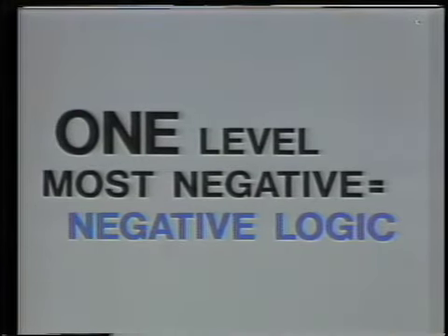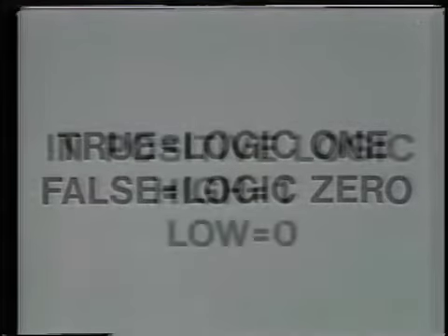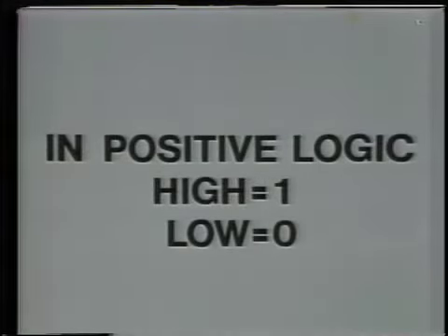The circuits shown in the remainder of the course all use positive logic, but there are many older schematics that were drawn using negative logic, so you should be aware of the existence of the two forms. In circuits where the logic levels are referred to as true or false, a true and a logic 1 represents the same thing, and of course a false is the same as a 0. The logic states called high and low refer to voltage levels, and it's necessary to know whether you're dealing with positive or negative logic in order to relate highs and lows to trues and falses, or to ones and zeros. We're using positive logic in all the following material unless otherwise noted, so any reference to a logic high is the same as a logic 1 or a true.